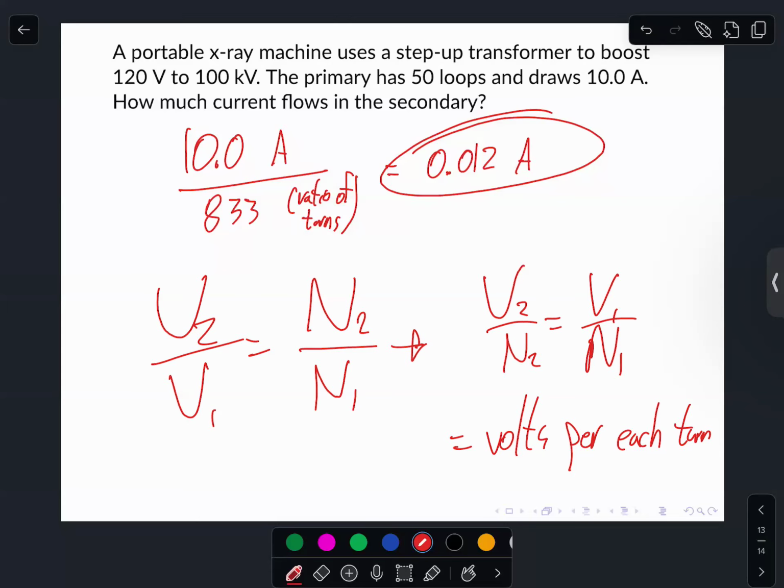You put 120 volts in, it pushes on 1 coil, it pushes on 10 coils with the same amount of push per coil, and then lots of coils multiply up. You've got more coils in the output than the input, so the same induced voltage is felt more times. That's all. And hopefully that made some kind of sense for those of you who didn't see what I said.